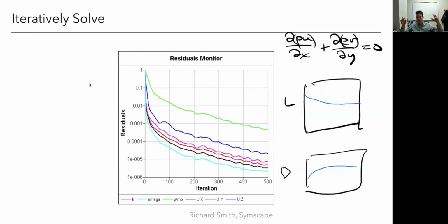streamline shapes, which we usually have in aerodynamics, because the projected area in the drag direction is so small, you need a very fine mesh to get a good solution, because you're just integrating around the shape, integrating pressures and shear stresses if it's viscous.